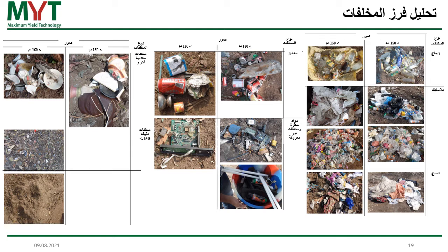For example, if you look towards the fine waste, you see mostly minerals and also earth. And if you have a very big amount of this fraction inside your waste, it doesn't make sense to burn this kind of stuff. So you would like to exclude the minerals and the fine waste from your incineration process, of course, as well as the other minerals and metals, which do not make sense here. And when it comes to the plastic, you see that you still have enough material for recycling, which you can use differently.